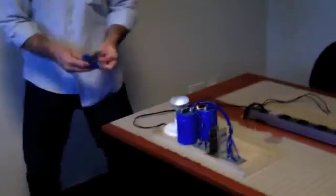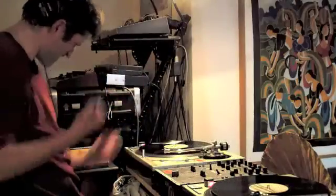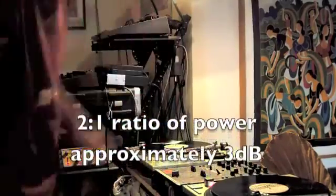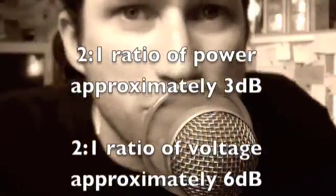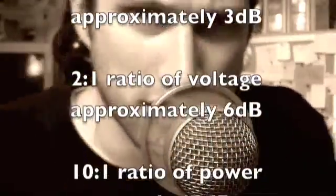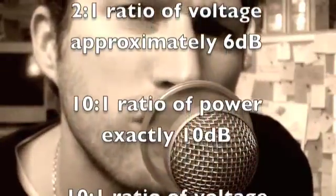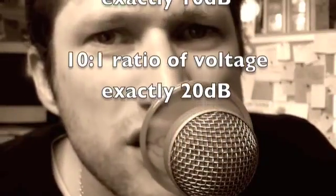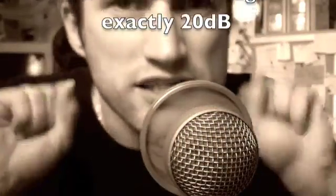So here's the shortcuts you should know to calculate decibels on the go. A 2-to-1 ratio of power is approximately 3 dB. A 2-to-1 ratio of voltage is approximately 6 dB. A 10-to-1 ratio of power is exactly equal to 10 dB. A 10-to-1 ratio of voltage is exactly equal to 20 dB.